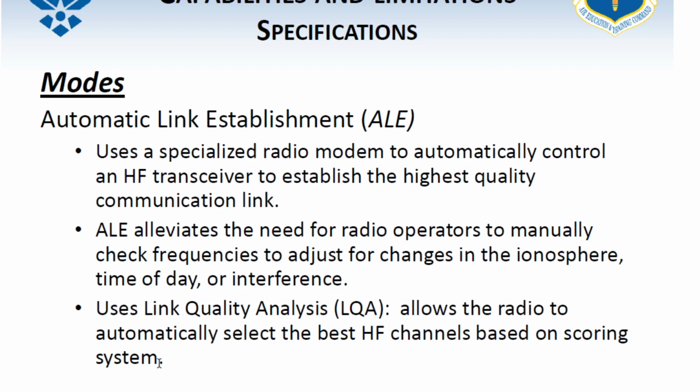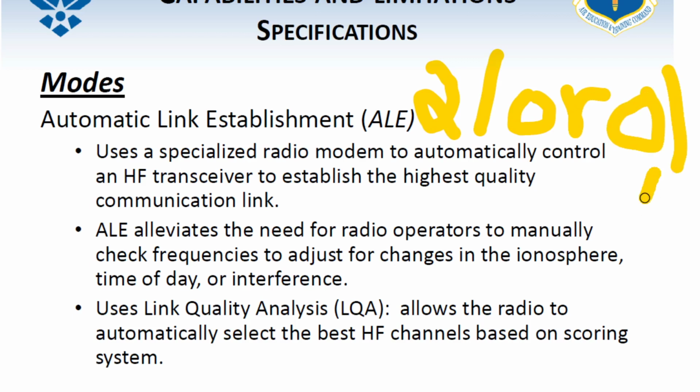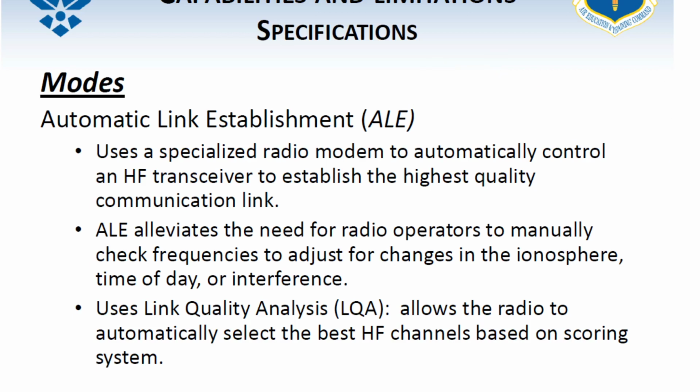All right. So ALE, that's automatic link establishment. It uses a specialized radio modem to automatically control an HF transceiver to establish the highest quality communication link. ALE alleviates the need for radio operators to manually check frequencies and adjust for changes in the ionosphere, time of day, or interference. It uses link quality analysis, which allows the radio to automatically select the best HF channels based on a scoring system.